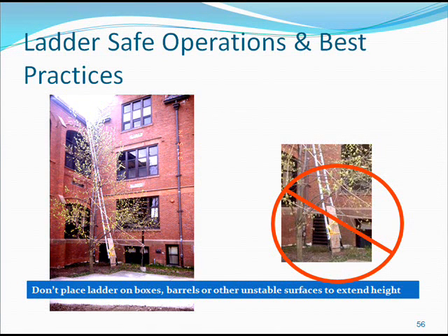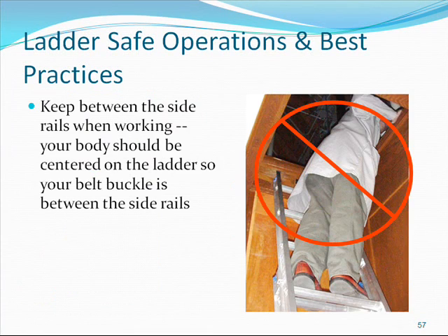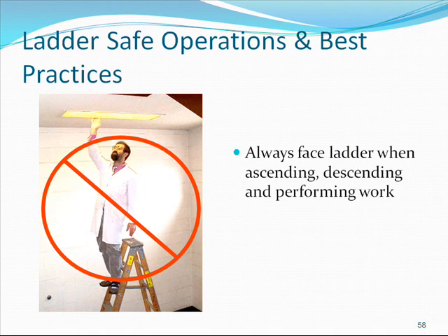Do not place a ladder on boxes, barrels, or other unstable surfaces to extend height. Keep between the side rails when working. Your body should be centered on the ladder so your belt buckle is between the side rails. Always face the ladder when ascending, descending, or performing work.